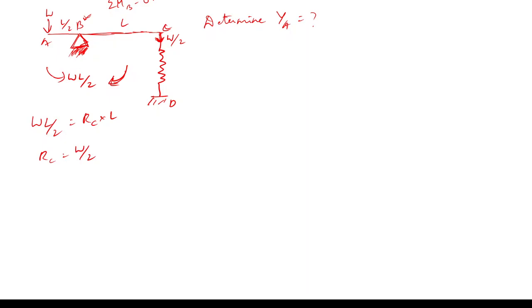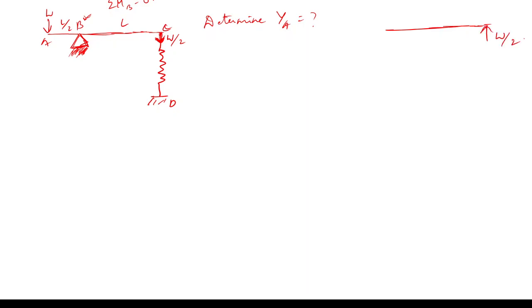Sir, in the internal energy calculation, sorry, U calculation, we have to include the effect of the strain energy stored in this spring also. Yes, because here you are having the beam reaction only, which is acting on the spring. For example, if I isolate the beam, you will be having a force which is equal and opposite, W by 2, exerted by the spring. Correct?